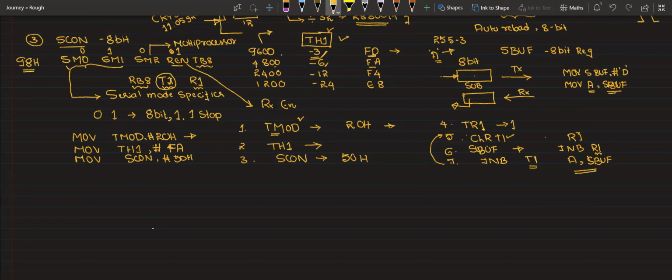That is the mode. So then set bit TR1. That means timer started. Your data rate started counting. Then again, instead of sending one character, we can send multiple characters. Like let me send Yes, 3 characters. Move A comma hash. Directly you can mention the character Y.